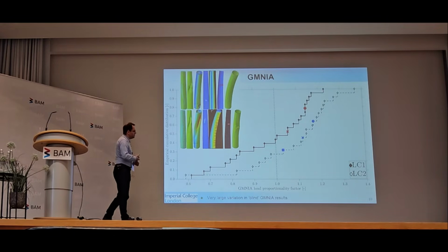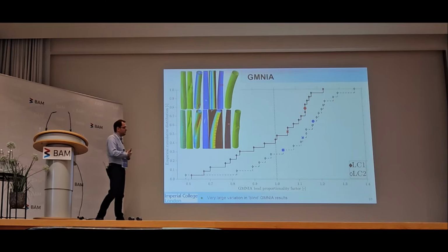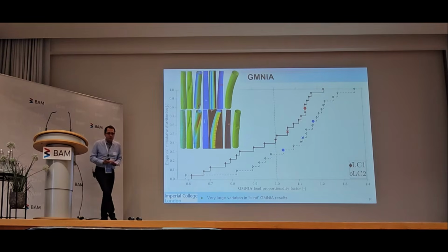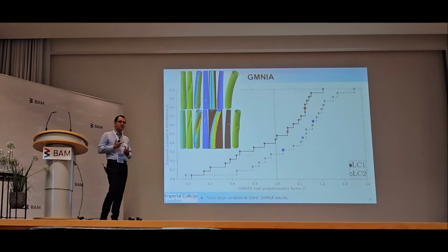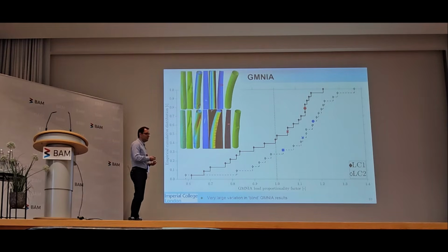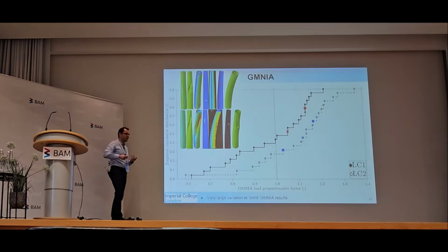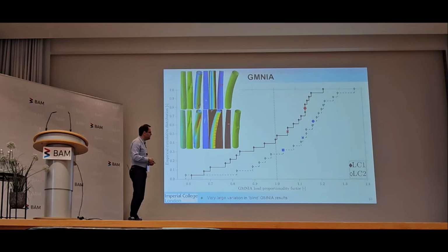I mean, okay, so the variability comes from different imperfections that people assume, but also from different ways of applying an amplitude. What does an amplitude mean for that imperfection? What number to take? Which version of the Eurocode did you look at? Because there was the 2007, the 2017, and now the 2024 version. All of them give a slightly different outcome. It was also what do you take as the termination point. Is it which point on your equilibrium curve is that? All of these things combined to give you this variability.